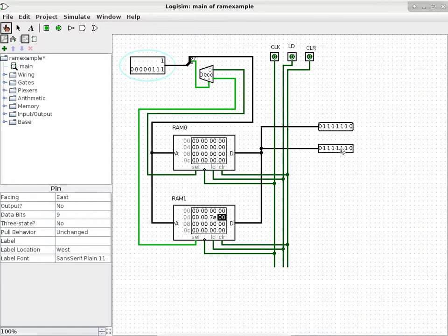What did I say? 2-1. So we'll specify a 2-1 here. This is 2, and this is a 1. And then I have to clock again, right? Change the clock, going back to 0. That is how much work is involved to write to a location that is right next to the one that we just overwrote.